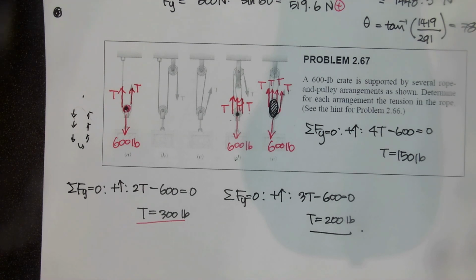Okay, any questions? Okay, so here the lesson is if we use multiple cable segments, then cable tension reduces, right? So it's more efficient. We can use thinner cable to pull the same weight, right? From the engineering point of view. And then another important thing is when you plot the free body diagram, we have a choice to choose the best point to plot the free body diagram. If you choose the wrong point, then we will not get anything. But if you choose a good point, then we can solve the problem easily. So engineering, statics is also based on strategy, right?